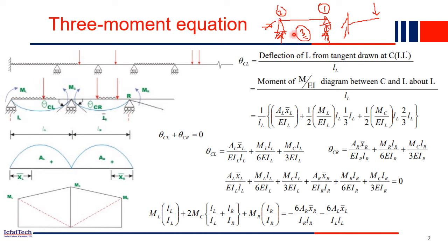If a structure is indeterminate, for example, if you take this simply supported beam, instead of this end being a roller, if this end is also a hinge end, then in that case you have two unknowns here, and in this support also you have two unknowns.